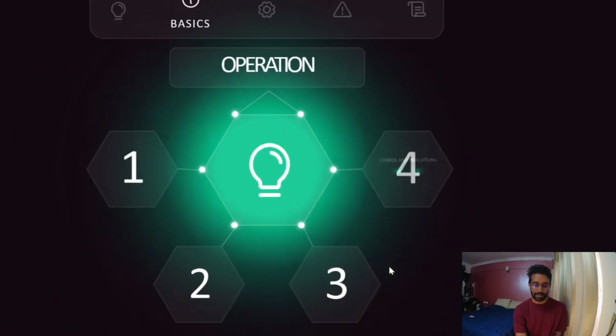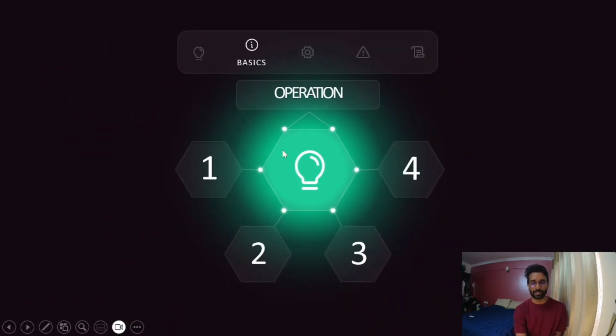So this in total is the basic operations of your hydraulic system. We have completed the basic operations, and now I hope you're all clear with how the green system works, the yellow system works, and the blue system works, the components and the indications, and what all control switches we have. Now let's talk about some examples.